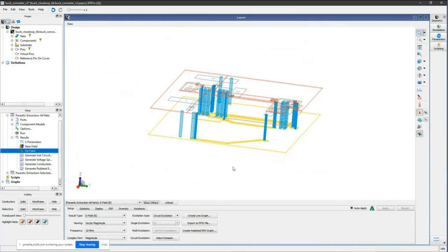And then all the vias, it's assumed that every piece of metal interacts with every other piece of metal. So it doesn't make any assumptions. And then this data is handed to the circuit solver, and the circuit solver says, okay, I now see how everything's connected. I'll give you the answers. So this is what we'll do a deeper dive on later when we do an EMI and a radiated analysis.